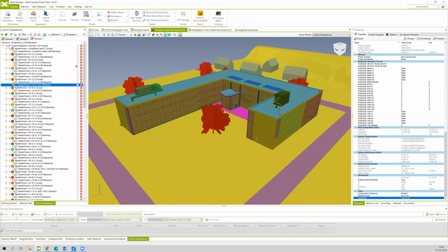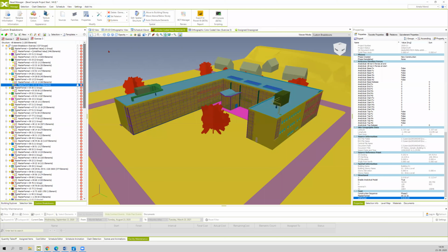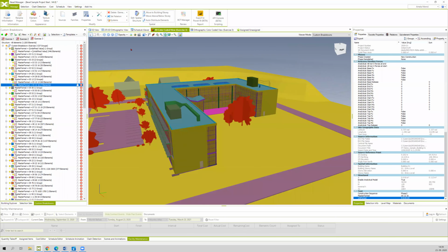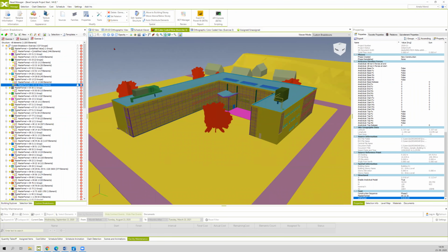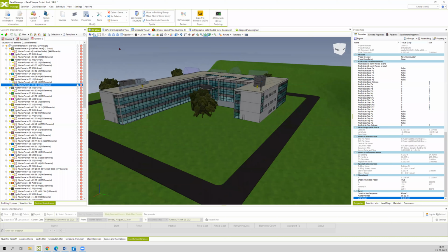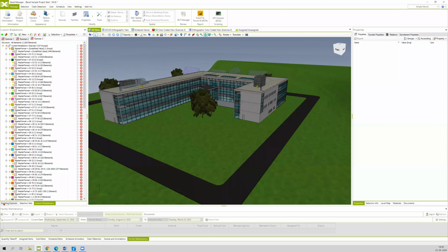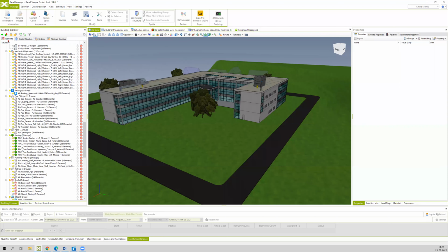So now we will go to the exercise 4, where we will add a continuous property, but we will not make a blank custom breakdown. We will first select different categories, and then upon those selected categories, we will create a custom breakdown. So go back to the 3D view, and then choose the Building Explorer palette and click on the Elements tab.